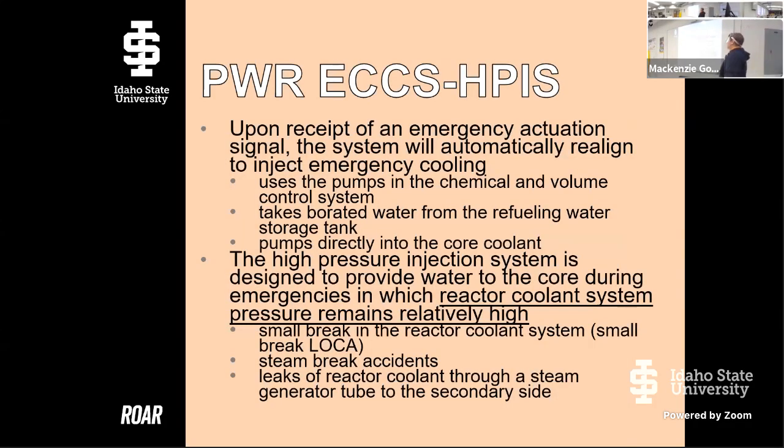So, emergency core cooling will automatically start injecting when you receive the right kind of emergency actuation signal. If you get warning in the control room of a LOCA, or if you get warning in the control room that the core temperature is above a certain amount, this is going to automatically start occurring. Essentially, it repurposes the pump. It takes water from a storage tank and puts it right into the core coolant, and it assumes that certain parts of that system are still able to pump into the core.